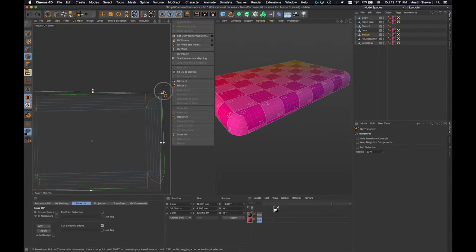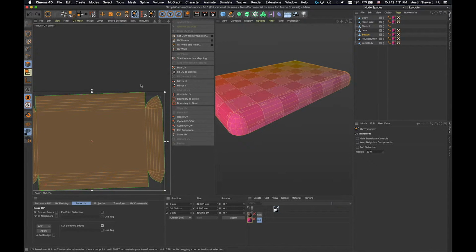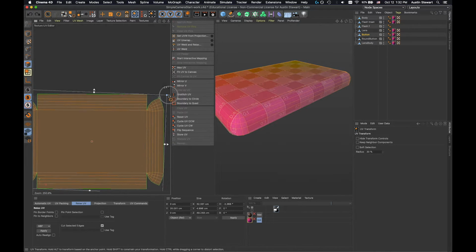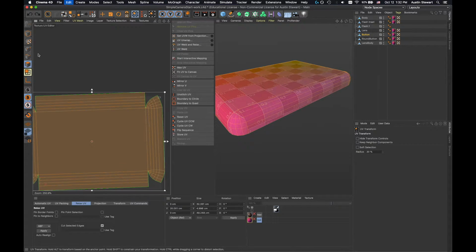One of the tricks to getting this edge to be straight is to zoom in enough and move your viewport around so that you can use the edge of the window as a straight edge. Right, so now that I'm here, I can say, that looks pretty good. Right? I don't know what just happened though. I'm going to go to polygons mode, make sure that's all selected. So what happened is I want to make sure that I do this rotation in polygons mode. Otherwise, all I did was rotate the seams of the object and the edges that I had selected.